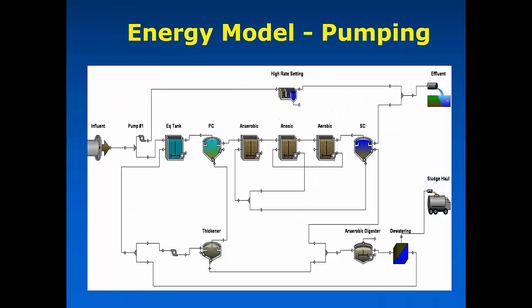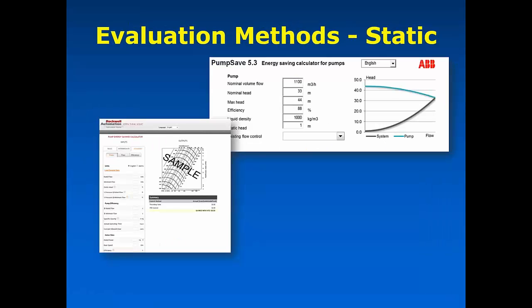And that calculation is done not only in the pump object that I just showed you, but actually in every place that you see one of these little pump symbols in GPSX. So for a plant that you have, you can calculate an operating cost at any one of these particular points. And if you right-click on the object and go to the output variable menu and go to the operating cost menu, that's where you'll find all of this information.